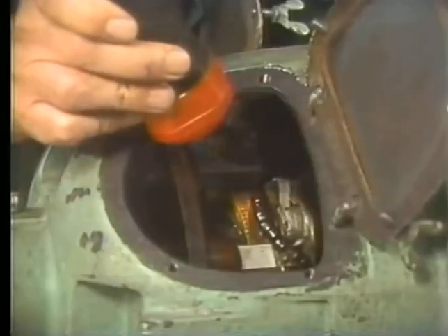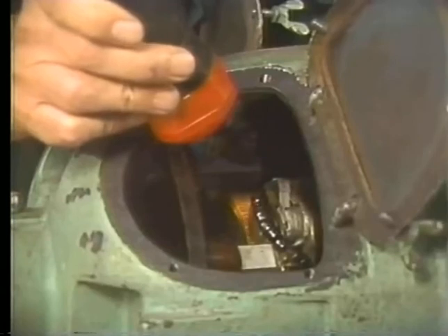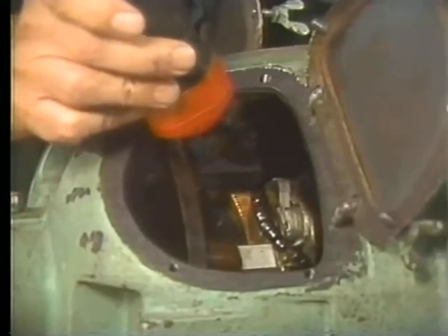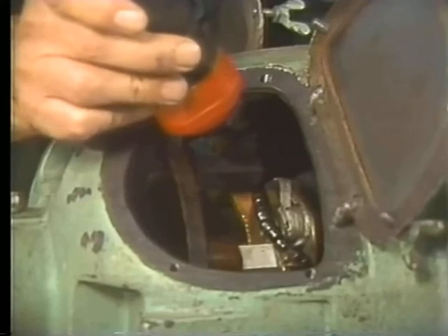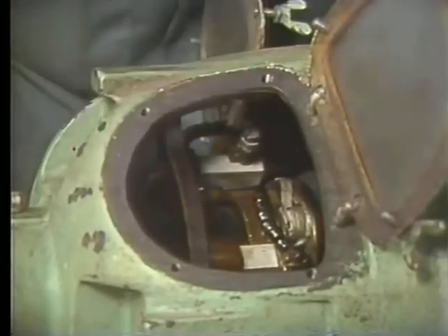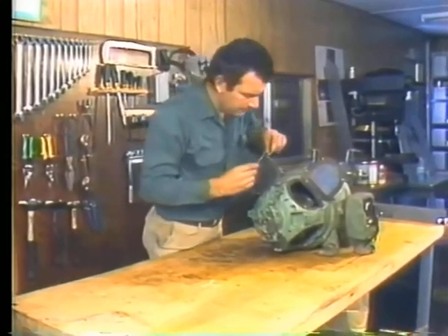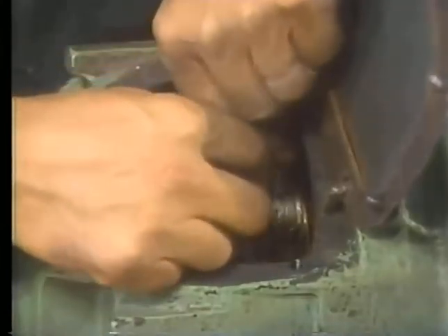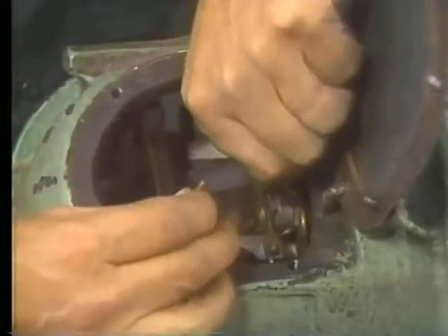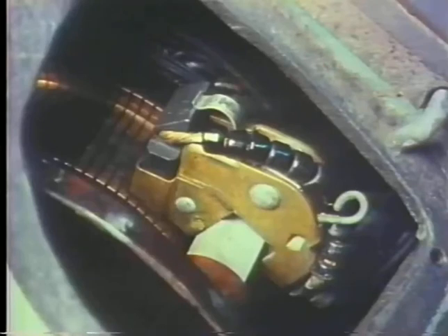As the brush slides on the commutator, it's going to wear, and as it does, carbon dust from the brush will cover other parts of the motor. That leads to problems. Any brush is going to wear down eventually. You've got to replace them when they get too short to do the job. Brushes can hang up in their holders and break contact with the commutator, or the pigtail can bind on the holder. That will cause the brush to break contact too.